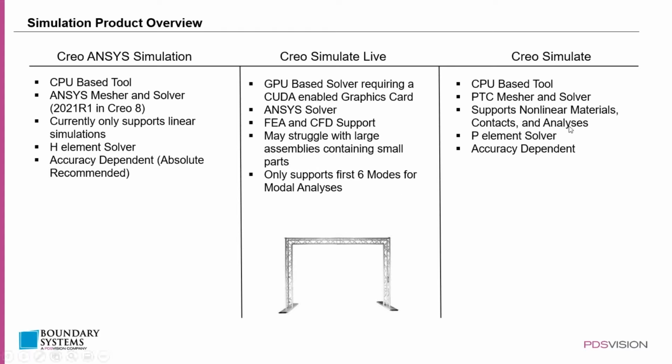Lastly, the tool we have is Creo Simulate. This is the tool that's been around for a while that PDSVISION has developed. It's an in-house tool. It is also a CPU-based tool. It has a mesher and solver developed by PDSVISION, like I said. And this is a full-fledged FEA tool. It has support for things like nonlinear materials, nonlinear contacts, and nonlinear analyses, which is currently not available in either Creo Simulation Live or Creo ANSYS Simulation.